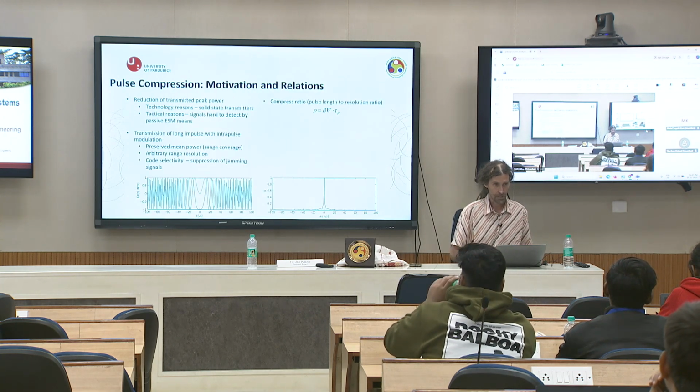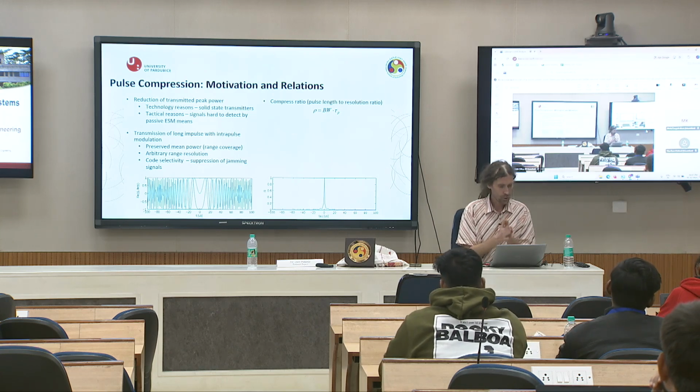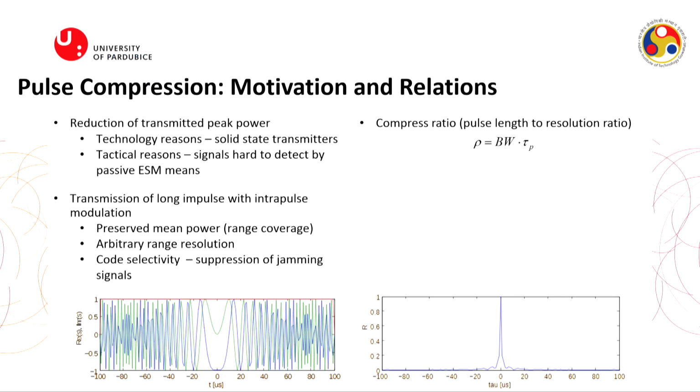Now I will talk about pulse compression. I already showed a rectangular pulse without any modulation. The autocorrelation function is a triangle. If I make a cross correlation with the receiving pulse, its spectrum is a sin x divided by x, sinc function. So the whole energy triangle has very poor resolution, because it is a triangle. It is really not narrow. You can agree with me. The spectrum of this is a sinc function.